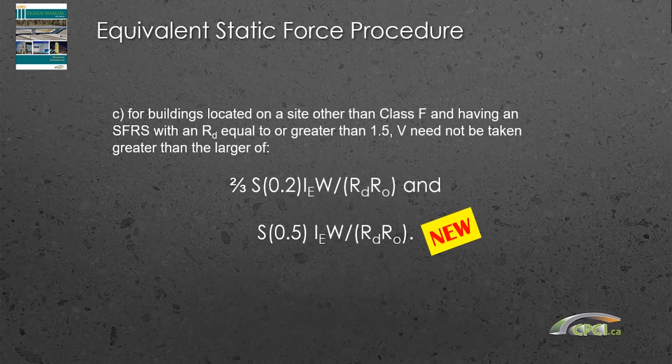And then this is a little bit new, these maximum cutoffs for your shear. They were basically put in, I guess, recognizing that short period structures usually have more reserve strength, and I guess the NBC 2015 allows such structures with short periods to have the 2/3 base shear cutoff, as long as it's detailed with a bit of ductility, and so that's where the 2/3 is coming from.